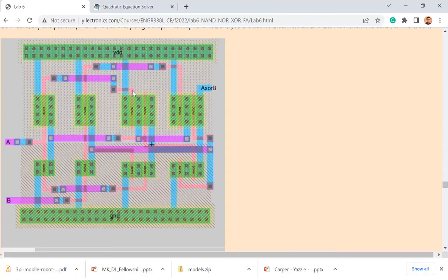So here's a gate, right? Here's a gate. And the blue one here is metal 1. It's metal 1. And they cross each other. So is there a short circuit? No, because there's no via. Okay, so it's okay. But based on the design of the circuit, I need to make the connection from the gate here to here. Two gates.